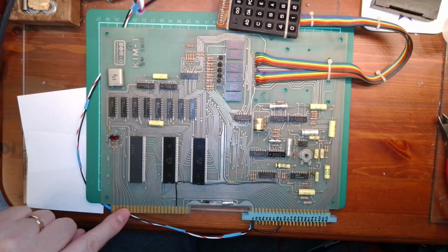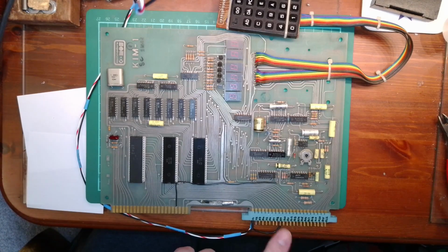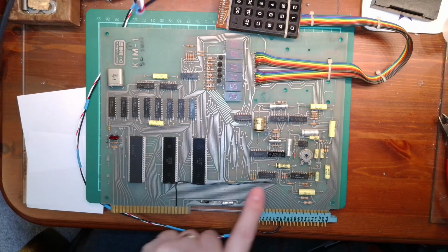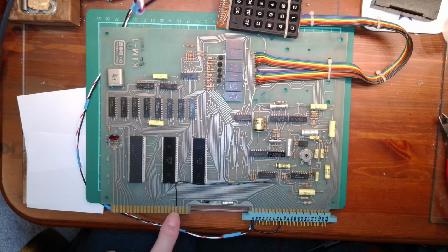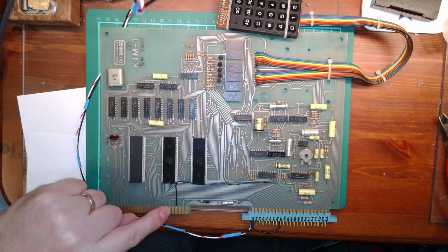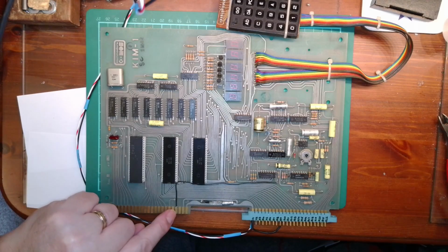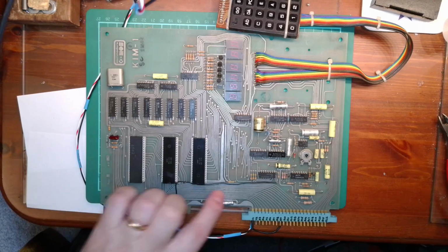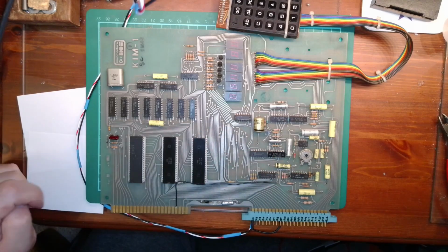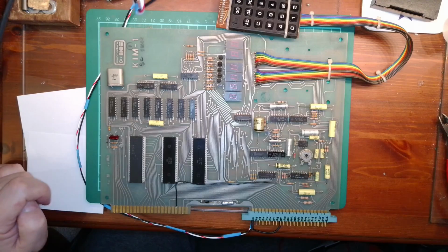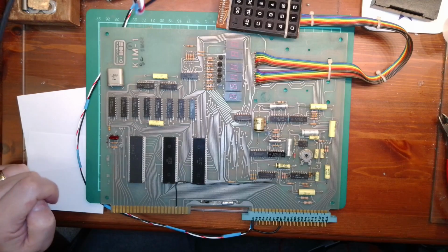So if you want to add anything that side, you have to fly a lead over here to another connector, whereas a power supply can actually be connected over here. So putting that lead over here to that spare pin there, there's 3 spare ones, then I can use that pin on the board to put the signal on there for the addressing decoder with just one board connected.